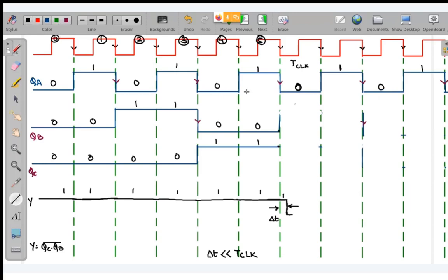So in the next clock pulse, this will become 0, and it will wait for the next edge of this QA, and at that edge it will toggle again. You can see this is a positive edge. So over here we will get the negative edge. So this will be the negative edge. So this also has become 0, and this will once again toggle over here.